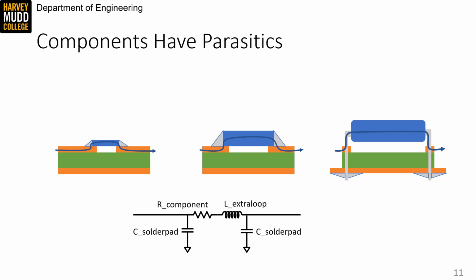And finally, small components are also easier to assemble for robots, not really for undergraduates, but that's okay. And they take up less board area, so many passives used in RF designs are in tiny, like 10 by 20 mil packages.